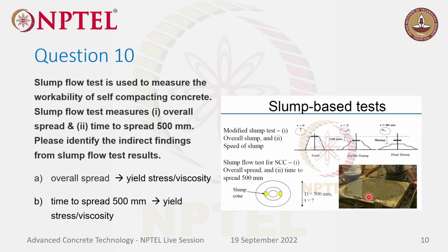So that was one of my learnings here. We do not want concrete which has very little resistance to flow. We need properly optimized resistance such that it has to reach that 800 mm as well. Then only it will not face any bleeding or segregation while flowing.